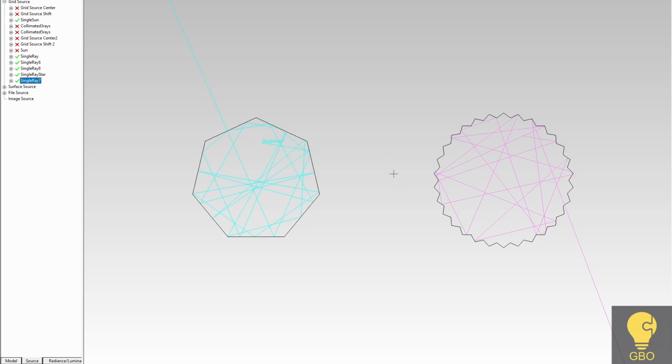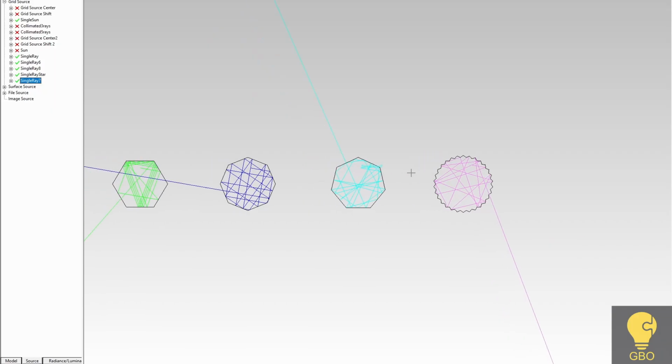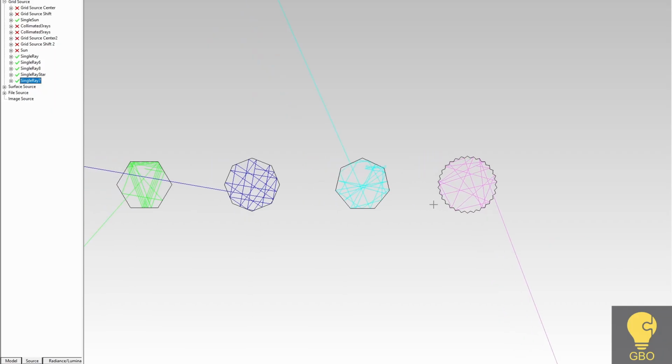So where is the problem? Designing a light guide with a section of this kind, with a very large number of facets, brings several difficulties. There is the practical question of how it would actually be manufactured, and there is the fact that we end up with a great many reflection angles that are potentially awkward or hard to control. If the component works by total internal reflection, we will have a very large number of reflections on the walls, with a progressive loss of intensity as a result.